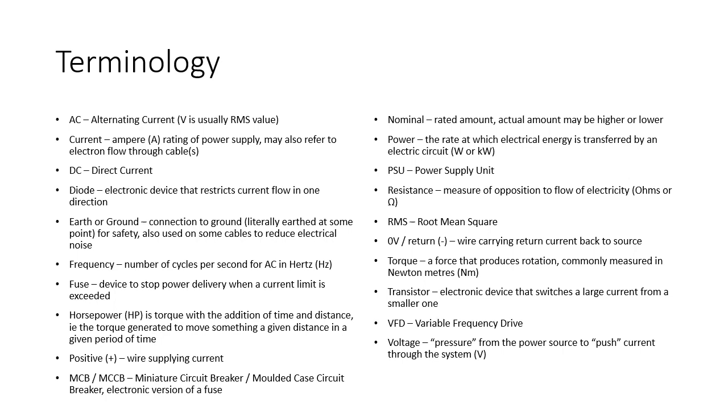And the final one there, voltage. Voltage is the pressure from the power source to push the current through the system. Higher voltage means higher pressure. And that's also related to current and related to power itself. But voltage is important because that's what we use, and we have to rate the VFD according to the voltage of the motor and the supply current. And we also need to take care of high voltages because high voltages can be dangerous.